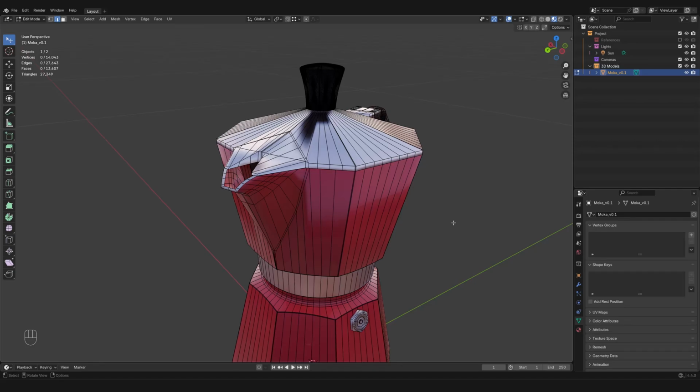And usual reminder, in the bottom left corner you have the screencast keys. And then I'm gonna press O, like on, and that is gonna turn on the proportional editing. Now, the proportional editing lives up here in the 3D viewport in the middle section, and it is this icon that has now turned blue. If I press O again, it will deactivate. So as you can see, it has several options. Although smooth is the most commonly used, very rarely I have had to change it.